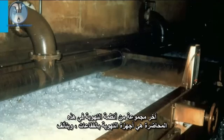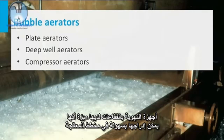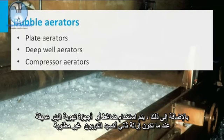The last group of aeration systems in this lecture are the bubble aerators, consisting of plate, deep well and compressor aerators. Bubble aerators have the advantage that they can be easily incorporated in the treatment scheme. Namely, the required energy is not extracted from the water phase, but given to the air phase. This makes the gas transfer much more flexible than in other aeration systems. Additionally, compressor or deep well aerators are used when the removal of carbon dioxide is undesirable.